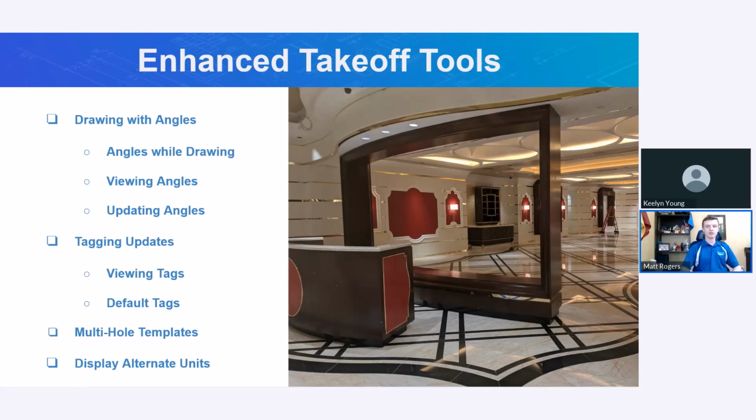Another nice little update, this is actually something that was requested after one of our recent updates. In one of our recent updates, we added the ability to add hole templates directly to our program. So you can drag and drop different holes like a kitchen sink or a faucet hole directly into a countertop. But now with this update, we can actually save multiple holes together and drop those in together. So something like a sink, we can include the faucet hole, save that as a template, and then automatically bring that into a countertop that we have.